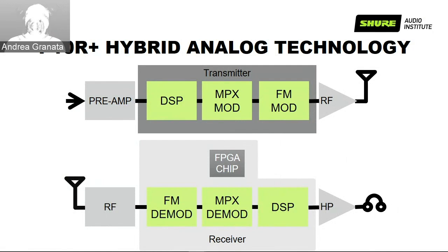So once you transform your box into a quadversity receiver, that device, that physical rack unit, is two channels in quadversity. But of course, in a system, let's imagine we have a band and the singer that loves to run on this ego ramp towards the audience. You may have the whole band in a standard diversity and the singer, maybe with a backup mic always ready, in quadversity. So you can mix and match and decide to have only certain systems in quadversity and others in normal diversity, but not in the same box.